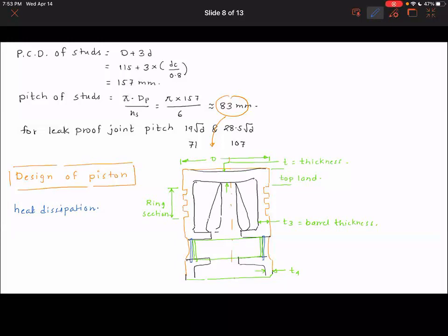But an important parameter that I want you to understand is that high heat conductivity is one of the important characteristics of pistons. If you look at engines which are slightly old and with a low power requirement, sometimes I've seen cast iron pistons used, but they have some additives or some sort of cast iron alloy that increases their toughness.